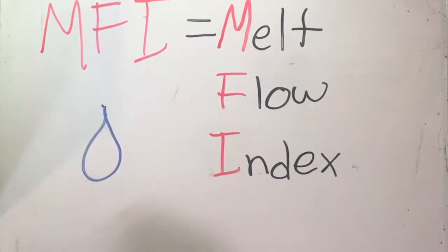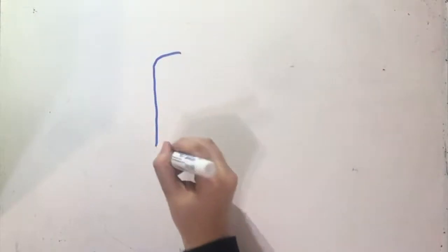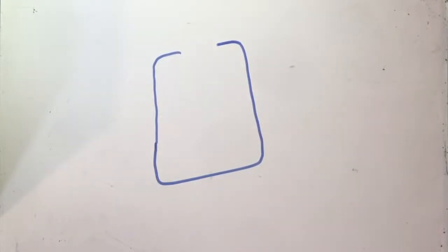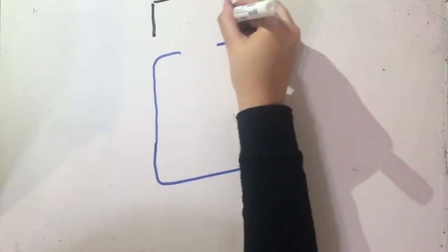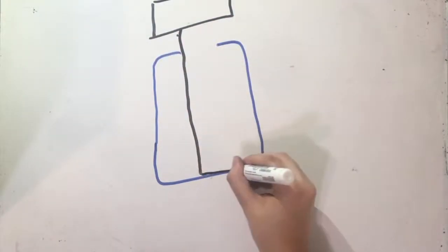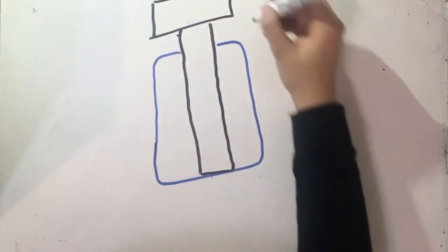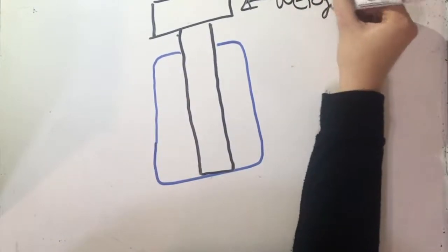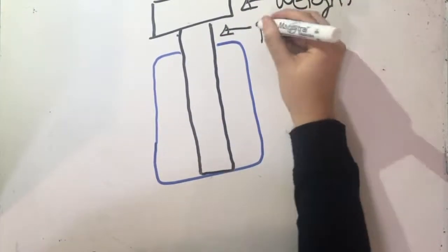It determines the amount of polymer mass in grams that pass through a capillary with a defined diameter and length. The procedure to do this test is by removing the piston of the equipment and adding the resin to the heated barrel, where it is compacted and allows the equilibrium. After a few minutes, the weight is added to the piston and the resin flows through the orifice at the